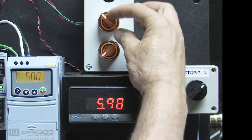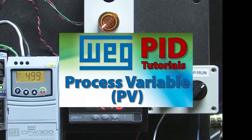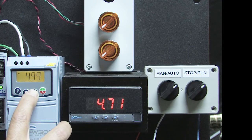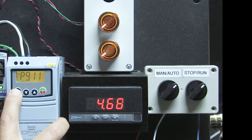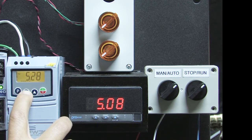I'll turn both switches off to get 5 psi, but the system goes to 4.7 psi. Why? Well, again, we optimized PID to work at 6 psi. But because our system is nonlinear, the farther away from 6 psi we get, the less accurate it'll be. We could go back and optimize the system using the techniques in this video, but it's a whole lot easier to just tweak the set point values in the table. So let's go to the first entry and modify it until we get 5 psi in our real system.